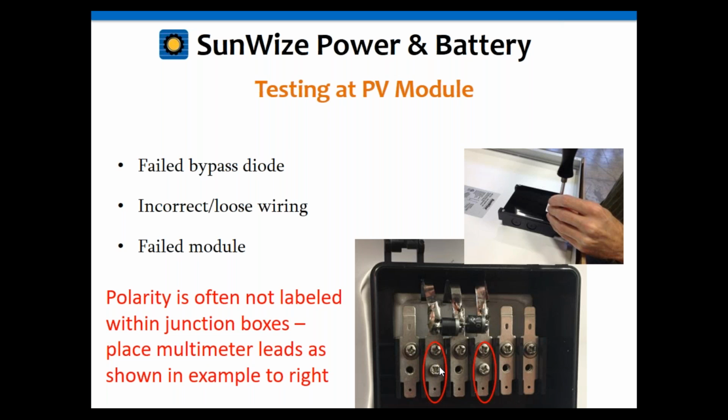Especially over time, I've had calls from systems that I've installed 5 years ago that all of a sudden are giving people trouble. What's happened is that through thermal cycling, as you go between night and day, you can have temperature swings of somewhere between 20 degrees and 30 degrees, depending upon where you are in the country. And it's even worse in the back of a solar module, because solar modules get really hot.